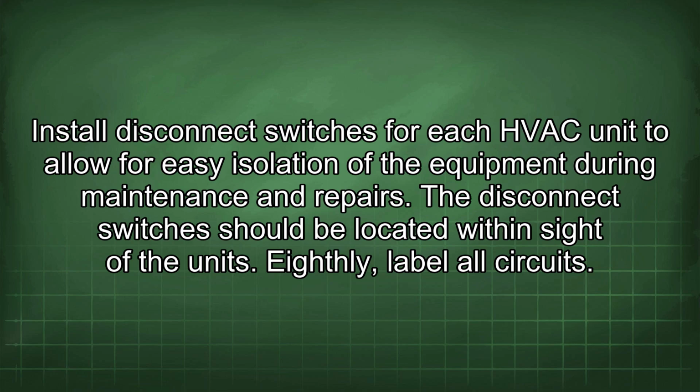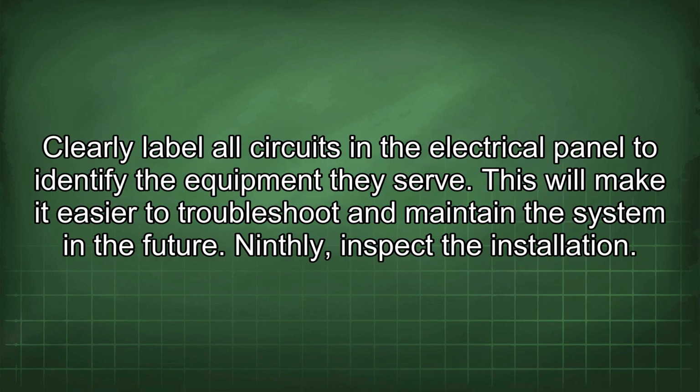Eighthly, label all circuits. Clearly label all circuits in the electrical panel to identify the equipment they serve. This will make it easier to troubleshoot and maintain the system in the future.